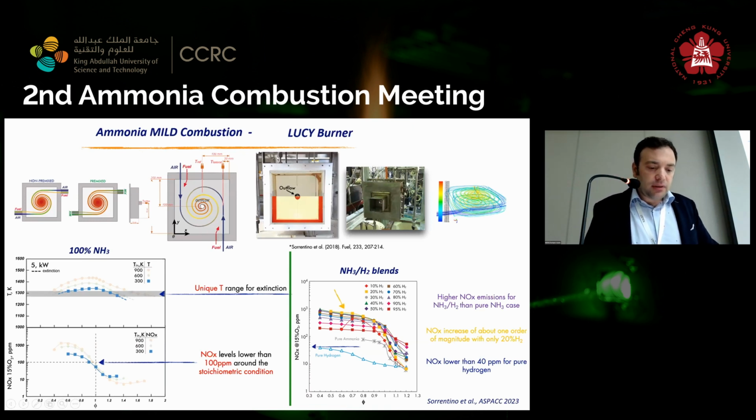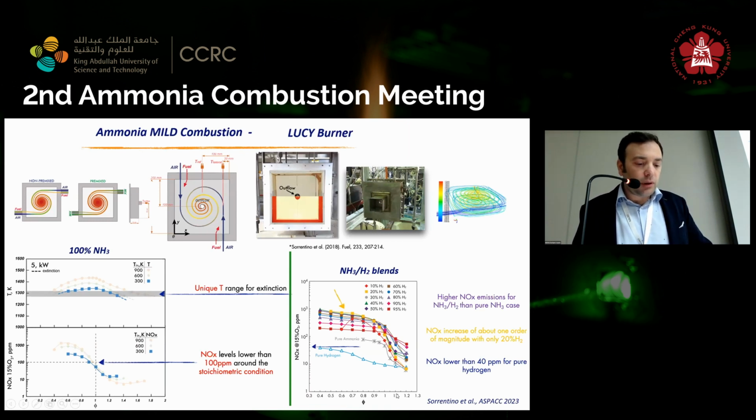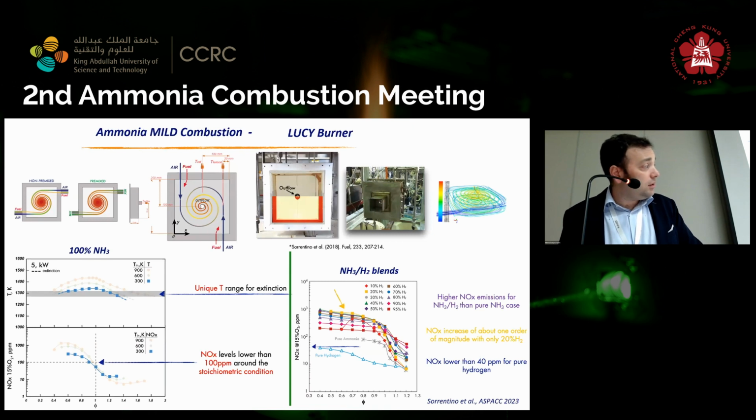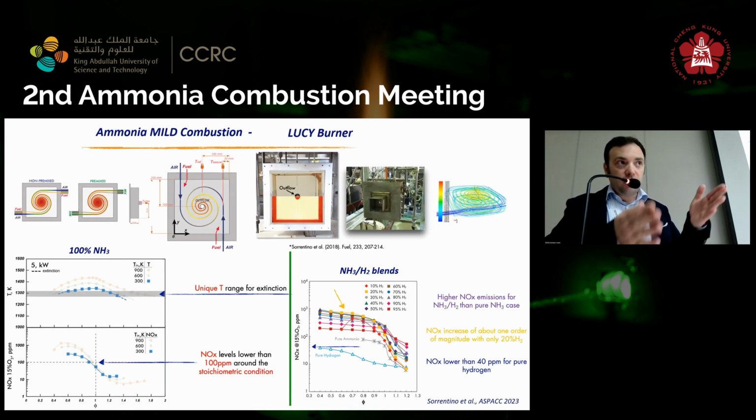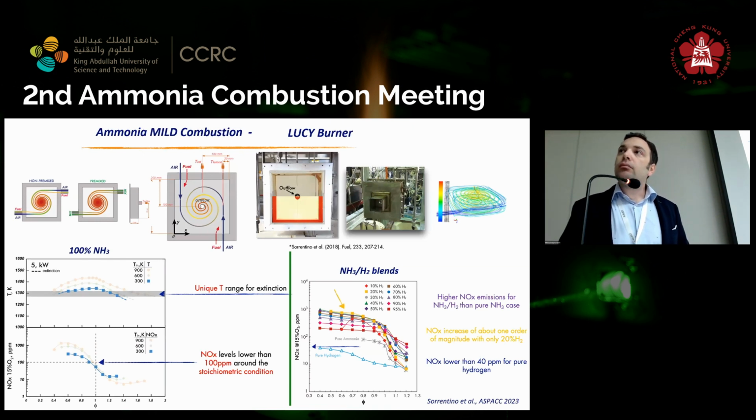I haven't reported it yet, but if you go for an equivalence ratio higher than 1.1, in all cases you have unburned ammonia that in some cases is higher than 200 ppm. Up to 1.05 of equivalence ratio, it is not too much, then it increases. So I guess the sweet spot is still consistent with the Kobayashi results. Yeah, we are almost in the same range. It's between 0.95 and 1.05. Of course, that has an advantage that you don't have excess air that you don't need. Yeah.